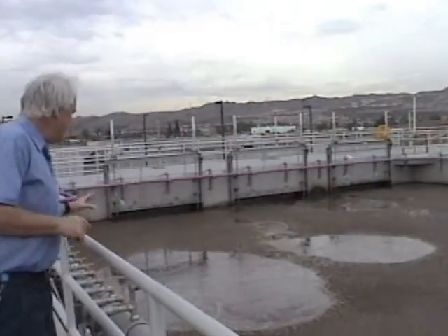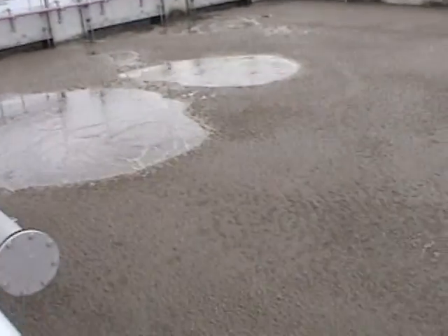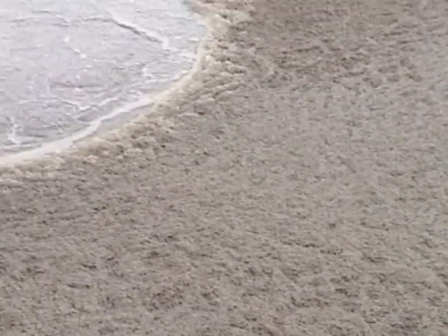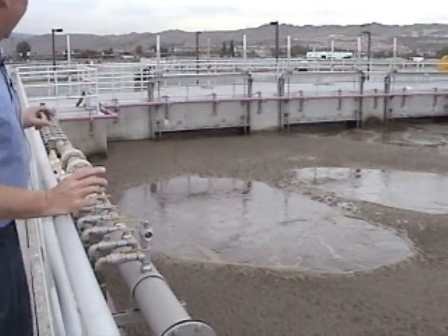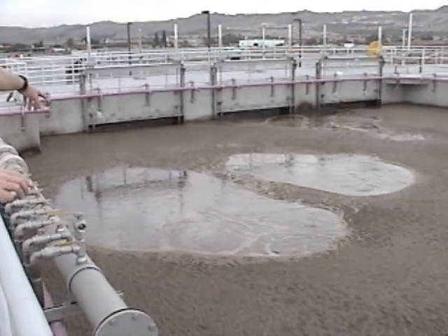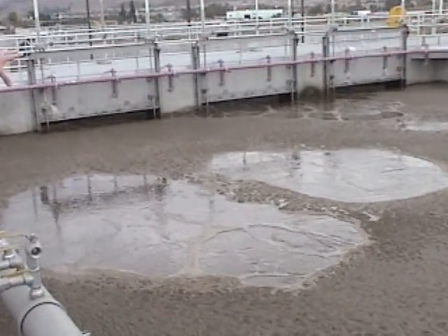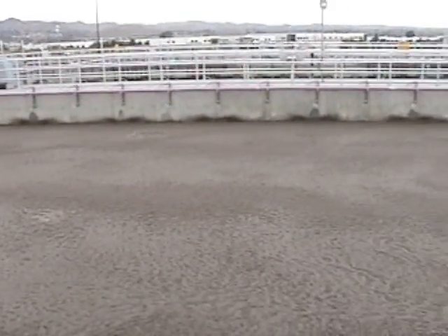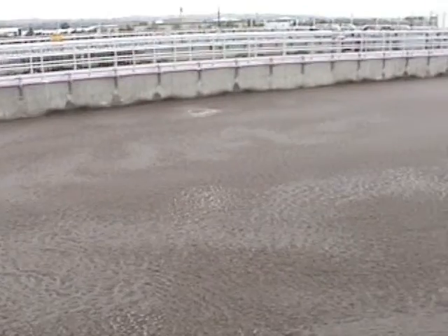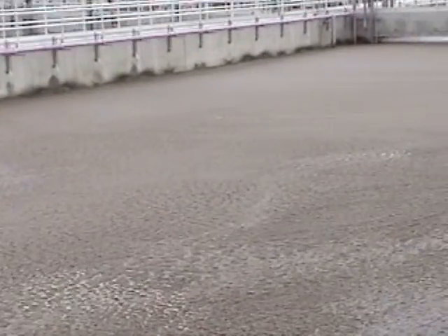As you can see, this basin here has a layer of foam on the top. This is Nocardia foam, and Nocardia is a low DO filament. So it's important, as you're making your rounds of the plant, to take a look at the basins. The basins will naturally have a little bit of foam on the surface, but typically you'll see just mixed liquor with a little bit of foam floating on the surface. But you can see there's a lot of Nocardia on here. So if you're out making your rounds and you see Nocardia foam on the surface, be sure to log it and let us know that you're seeing foam up on the surface of the tank.